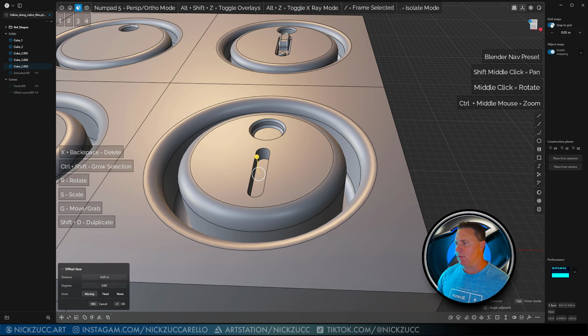See what we've got going on here for scale? Okay, this is just not going exactly the way I'm expecting. So I'll tap 4, I'll select this body, I'll put on move, tap V, go here, and then move this out just so I can see how big this thing's going to be, because I'm going to turn this into a shape. So I'm going to scale it again, tap V, go here, and then just scale it right about there. And then now I can move it, tap G, tap V again, go here, then just push this right about here. Okay, I think that's going to be good.